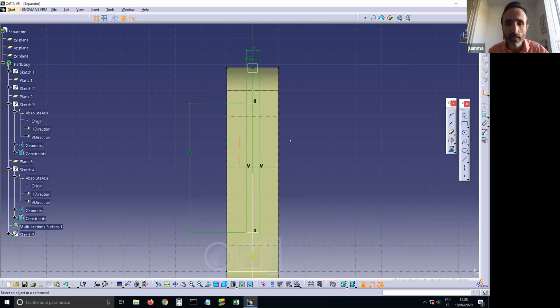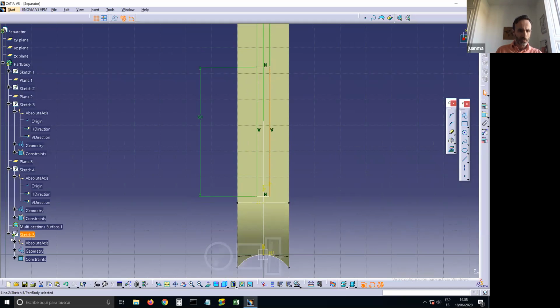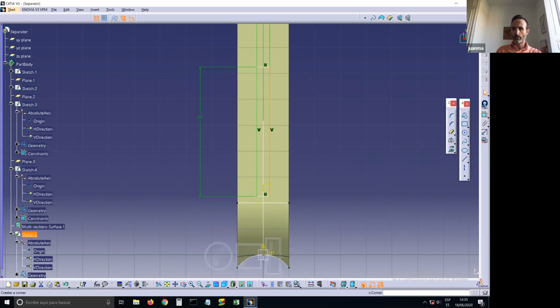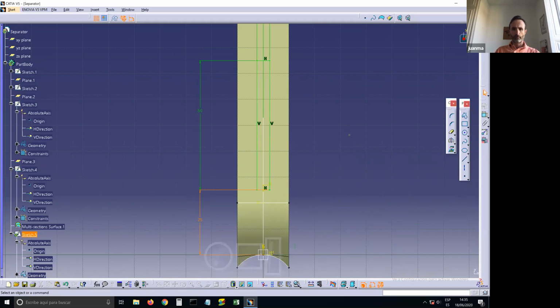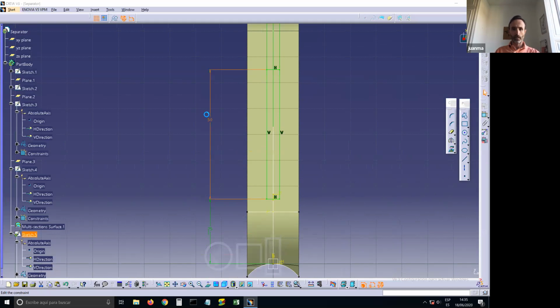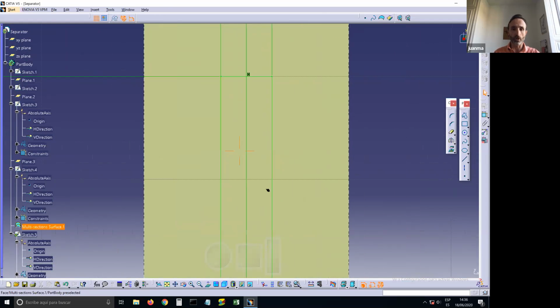And as corners, no, let me position the whole pocket with respect to the sketch. Okay, so I will define the length between this line and the horizontal axis of the sketch, so that I can set this length to perhaps 25 millimeters. Okay, I think I can make this a little bit longer. And you know that corners are the enemies of mechanical engineers, so I will try to fillet these corners also.